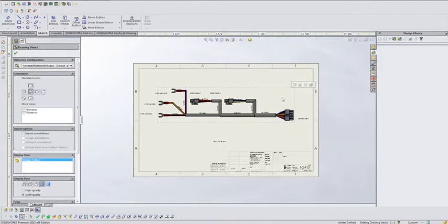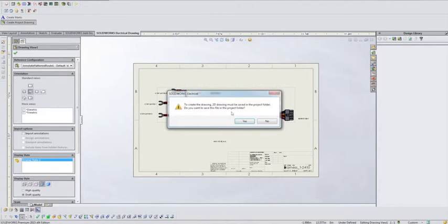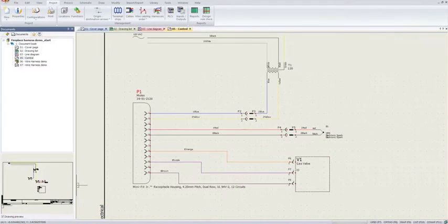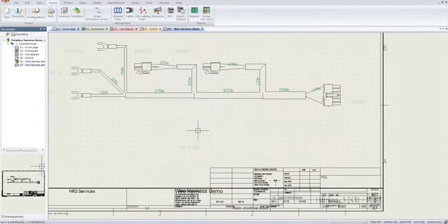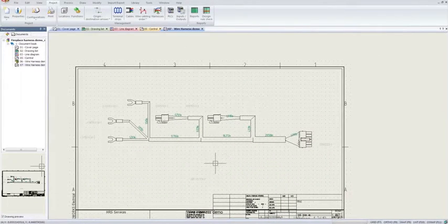And how we can do that is create a project drawing. So we're going to go to SOLIDWORKS Electrical drawing, and we're going to go to project drawing. What that's going to allow us to do is take in all this information here and put it into my SOLIDWORKS Electrical 2D, right? It's almost creating like a DWG file, for instance. Now if I pop back over here, notice that this is not something that I had to do manually, right? But it brings that in. So I have all of my information in here now.